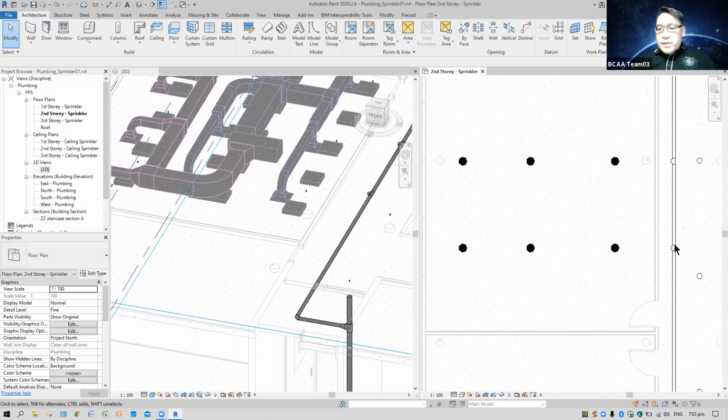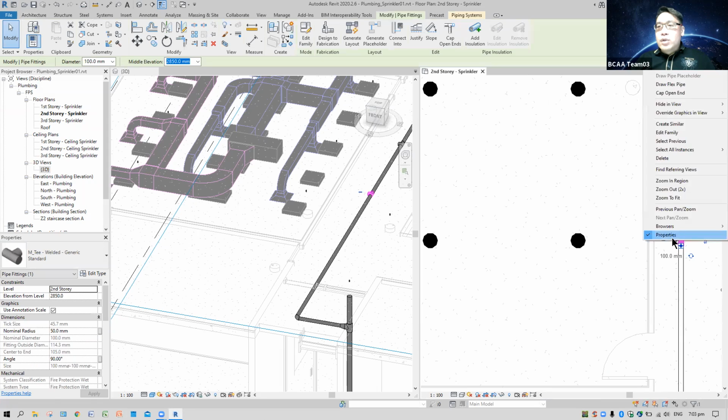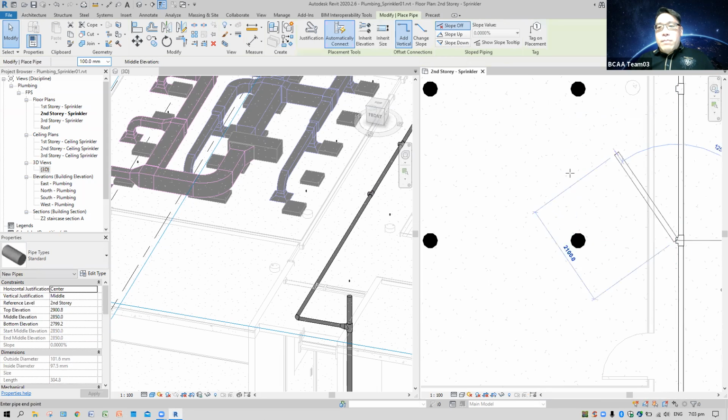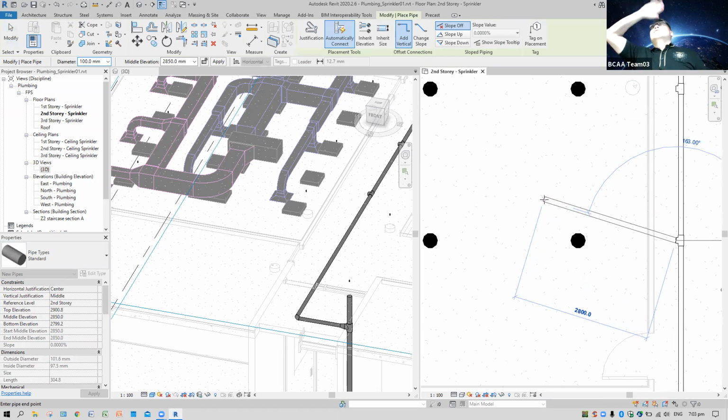One is I select this first, then point, right click, draw pipes. Now, of course, since it's only for three coming in, you can see in this room the pipe size is more like 40 or 35. I think it's like 40 or 30, right? As I say, the smallest is 40, right? Smallest you can go under 25, which is the pressure will be higher. So here I don't think they want that, because for pressure drop, everything is cheaper. Cost is there. So if you want 40 all the way, fine.